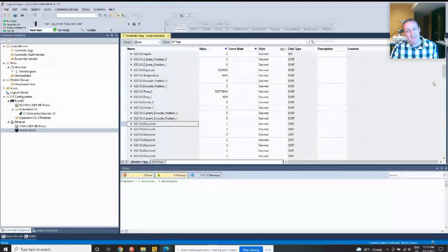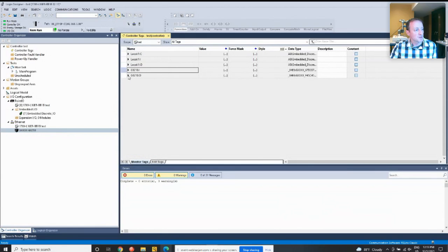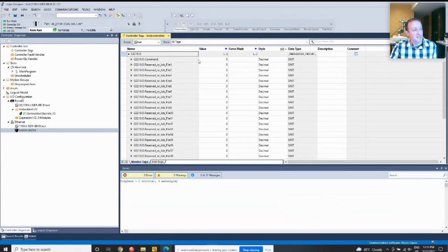Let's go ahead and send a command from our PLC to the machine vision system. And for that, we're going to use the other tags. Here, we're going to use our output tags. And we're going to send a command, and this is going to be our job file name. Now, to figure out what that command is, it's going to be some value. I want to reference our user manual because there's a lot of different commands you can send to start, stop the sensor, realign, or change the job, and those are going to have different command values.